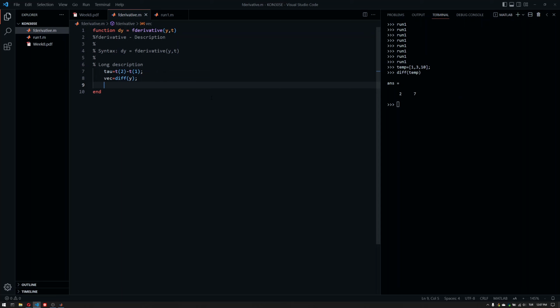And you might argue, well, it's not correct. Why can we do that? Well, the assumption in the zero-order hold method was that the tau value here, the time difference, should be going to zero. We should probably look at 0.1 seconds of time difference in the worst case scenario. In the best case scenario, it would be 1 millisecond, for example. And in 1 millisecond, we can assume just one sample. We can repeat just one sample because we have thousands of samples, and just one sample would not bother us that much. So that's the reason why we can apply this.